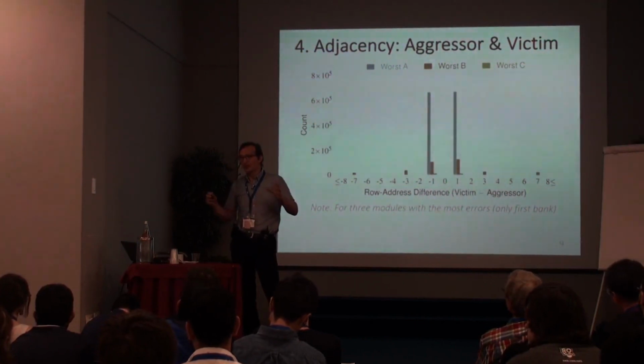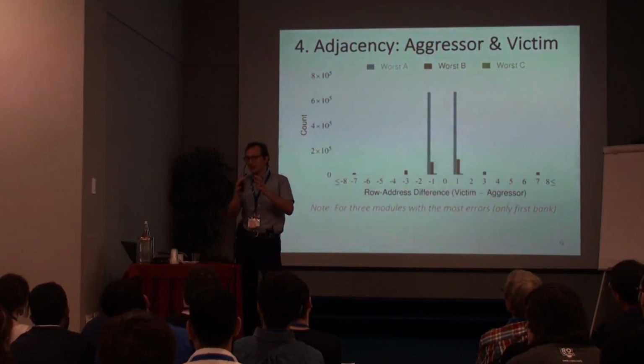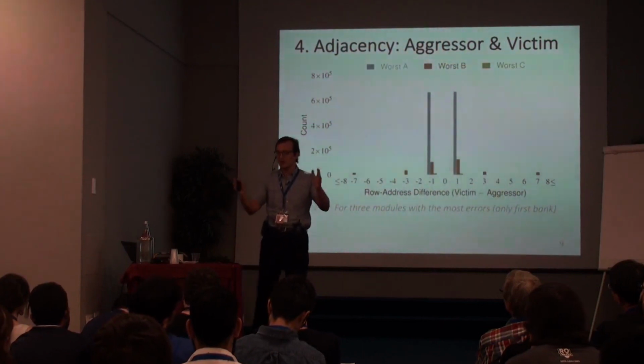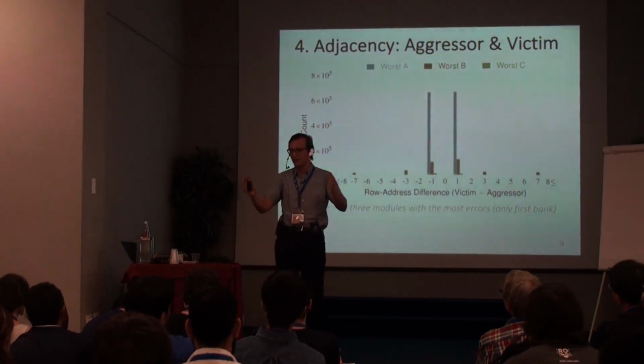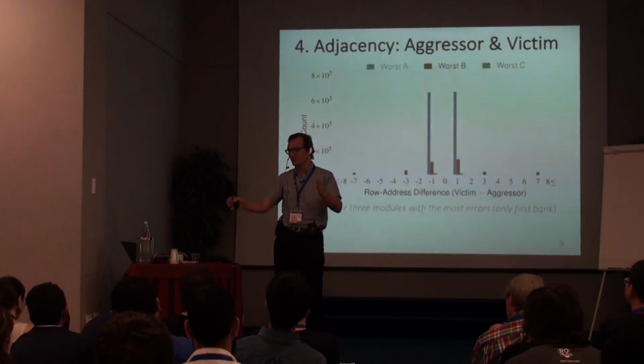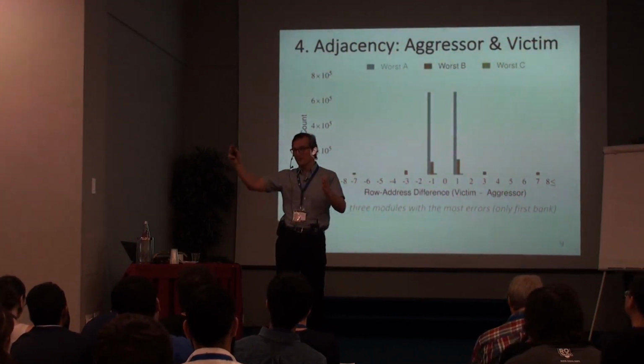Yeah, certainly. As you increase the capacity in flash memory, ignoring 3D NAND for example, what flash memory vendors do to increase the capacity is you have a voltage range in which you store the value. You can store only 1 bit by chopping it into 2 ranges, right? 0 or 1. You could store 2 bits by chopping it into 4 ranges. You could store 3 bits by chopping it into 8 ranges.